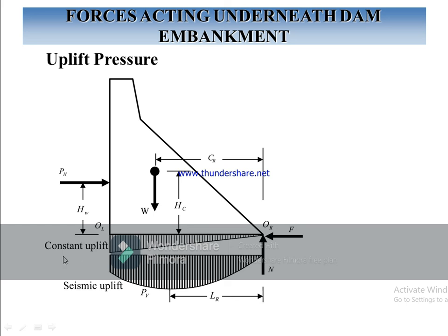Like here, for better understanding, pH is the horizontal force of the water acting from that point, and this is the W load acting downward, and this is the uplift pressure, which is constant uplift acting due to the water level, and this is the seismic uplift, because seismic actions also produce uplift pressures. When the uplift pressure is more than the dam's resistance, the bearing capacity, the weight, then the dam will be lifted.